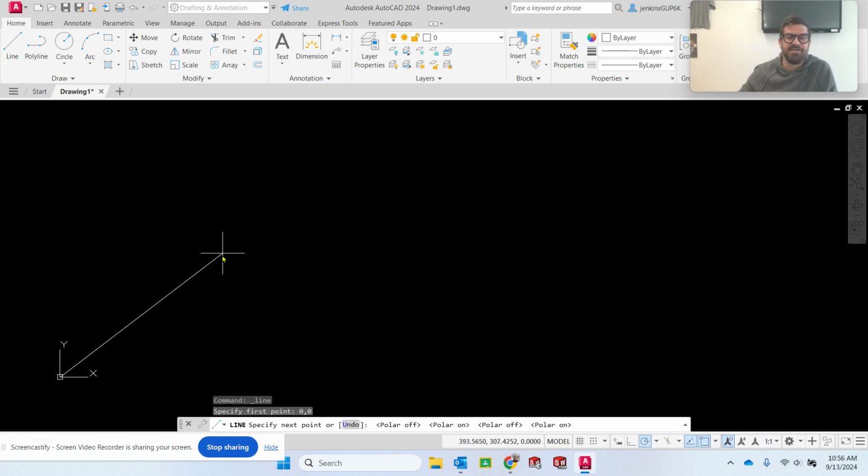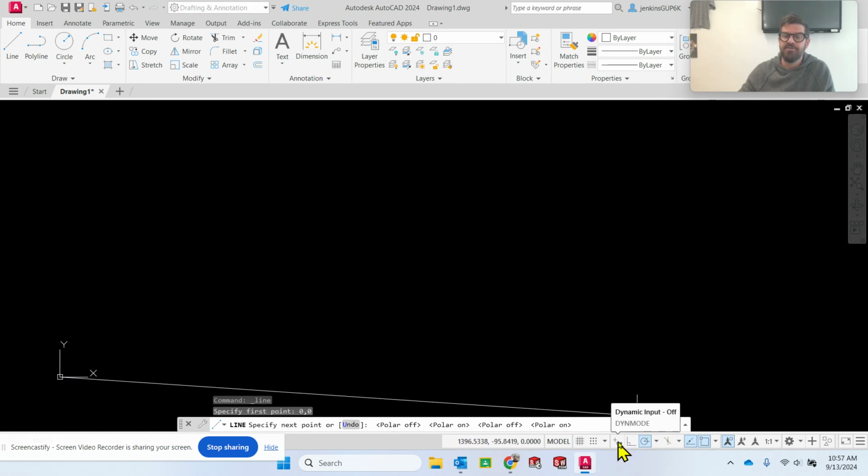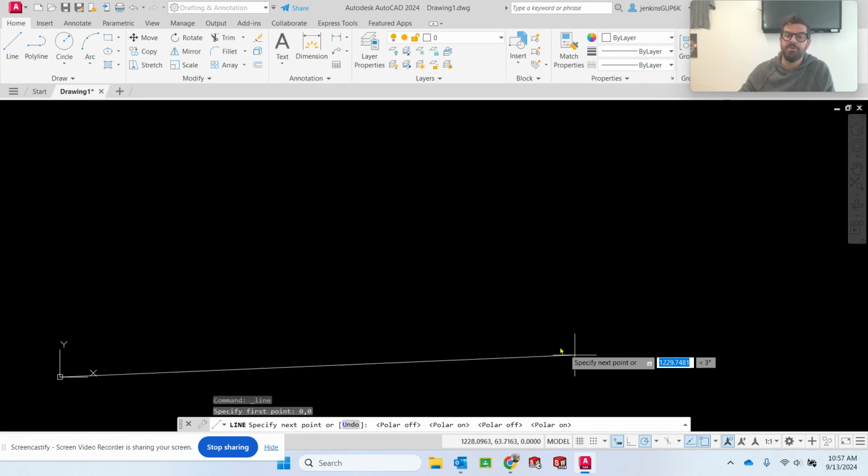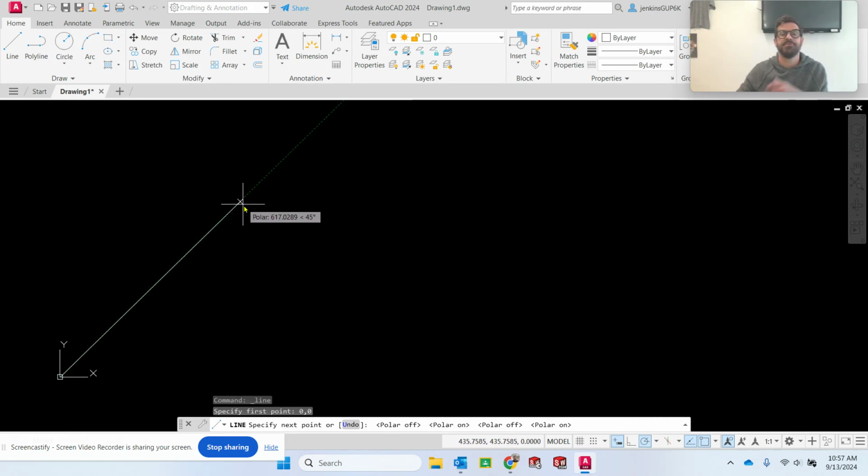One other thing you notice probably as I'm moving around. Right now, it's hard to tell how long my line is. Like in the first drawings, there's one line that's 46 units long and one that's 42 units long. I can't tell that right now. Something you can do to change that is if you go down to here, there's a little setting button called the dynamic input, on or off. If it's blue, it's on. It was off. But if I click it and make it blue, see what happens now, right?